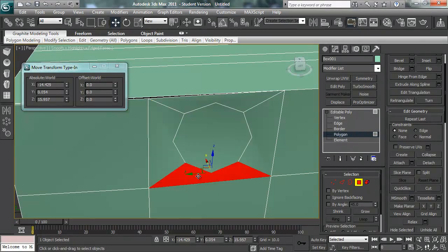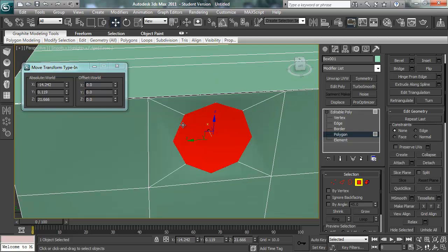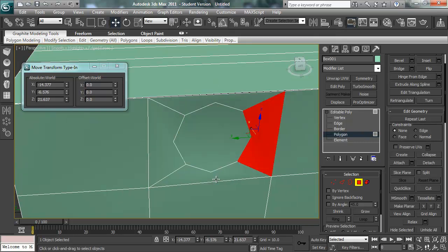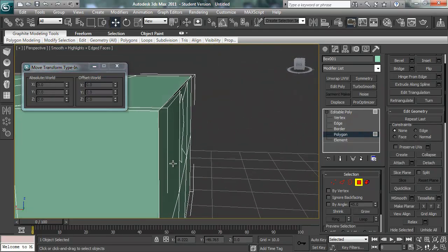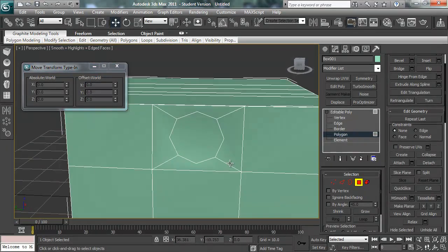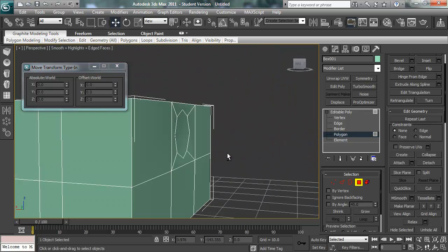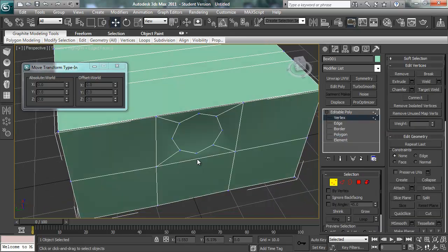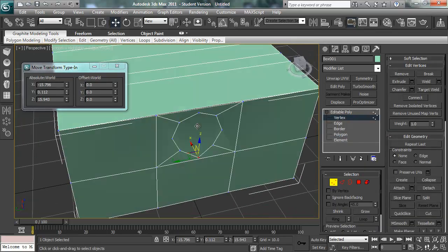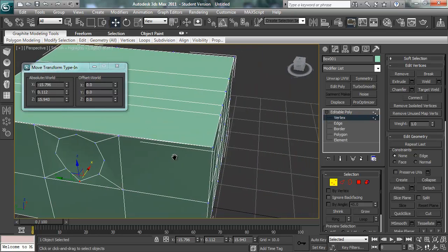So it's not a bad idea to make a little shortcut for it, something I tend to do. I think I have mine as Shift and the little key on the left of Z, and you can just run around all your geometry firing a quick Make Planar on each of them, do it enough times and they end up pretty much flat. Even if they might not end up exactly where you want them to be, that will help make your geometry flat.